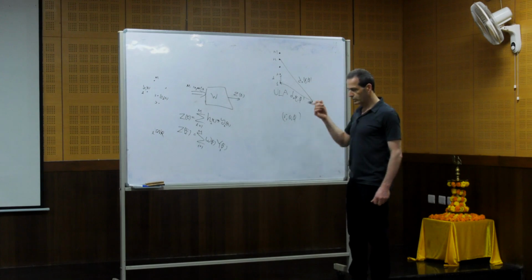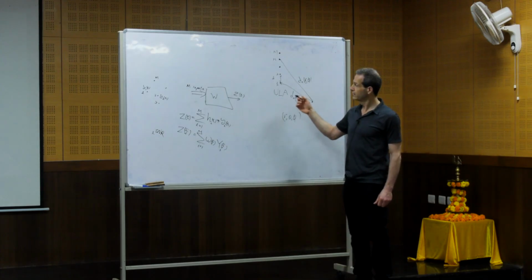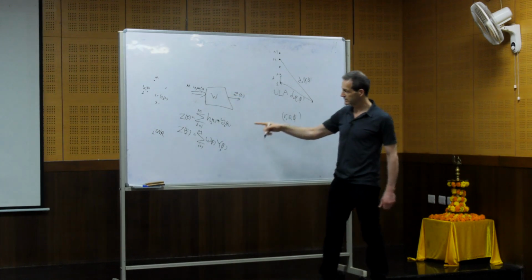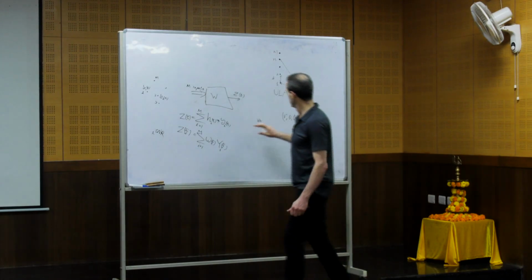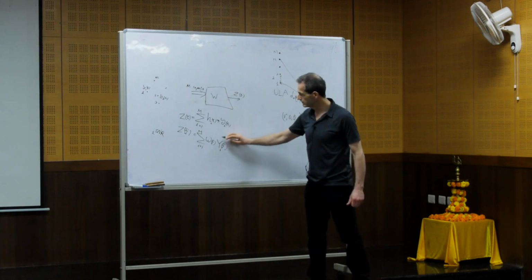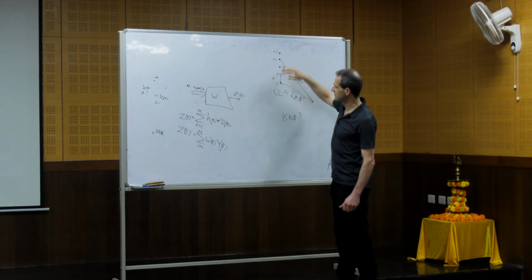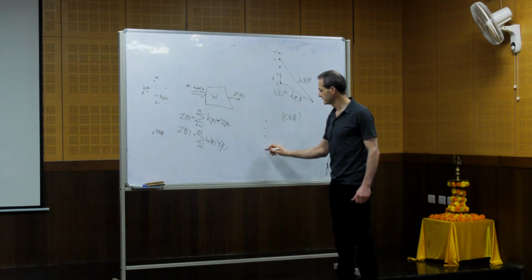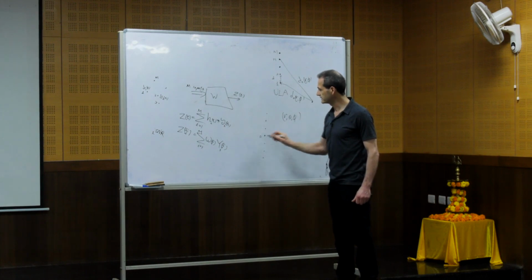Okay, so what does it mean, directivity pattern? It means the strength of the signal at the output of the beamformer. So if we use certain weights, and we take the summation of the signal that impinges on the sensor array, let's assume that we have an odd number of sensors, and this is sensor number 0.